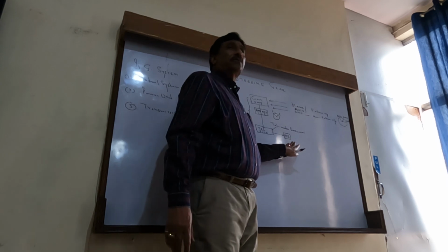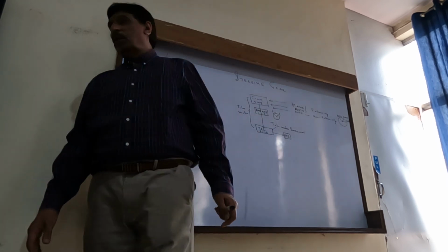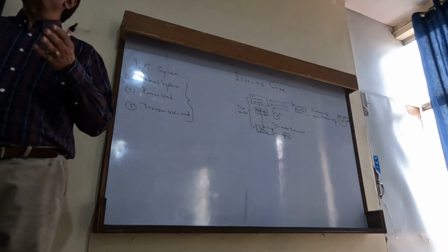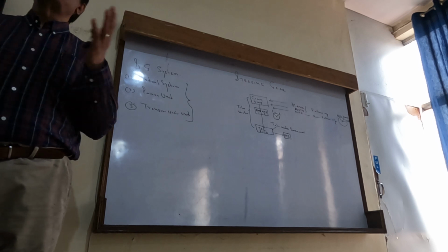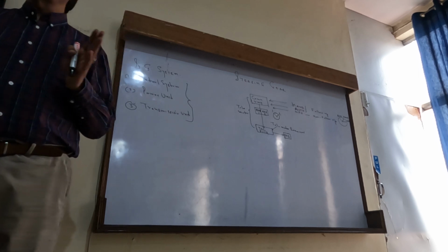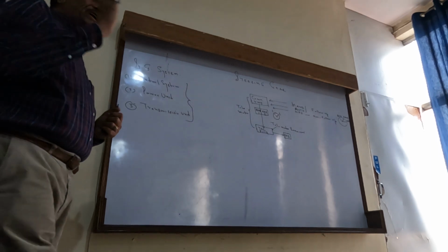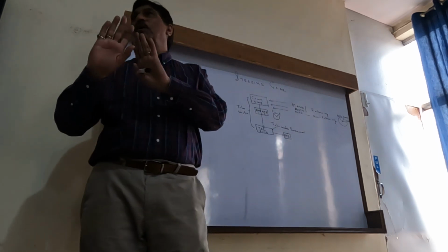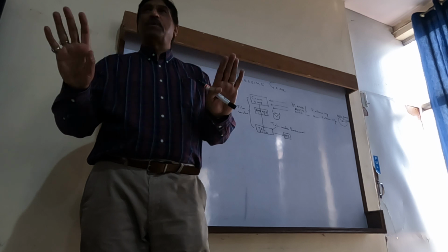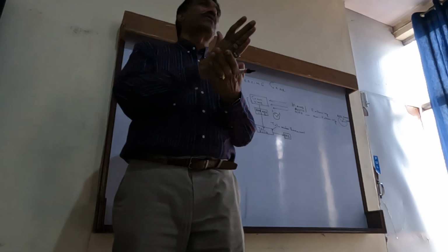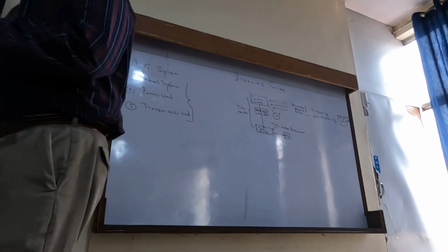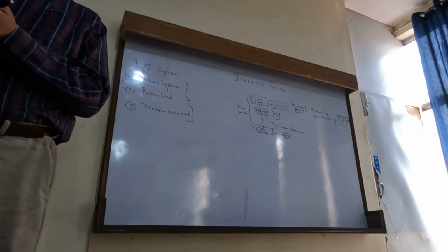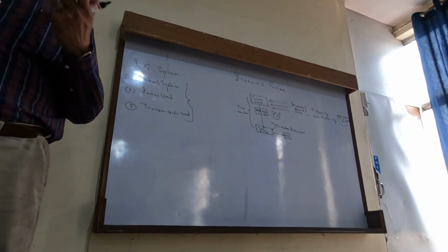So hunting gear is an equipment which is a control and shut off device. When we say control, that means as long as the rudder is not at the correct angle that you want, it will control. It will give a movement to the rudder. But once that desired angle or helm has been achieved, this same system will put the system to rest, in equilibrium, because you have achieved it. Now the rudder will stay at that particular angle. If you wanted 10 degrees, then at 10 degrees it will be hydraulically locked so that it should not move from there. So we use the term hydraulically locked. That is the purpose of hunting gear.